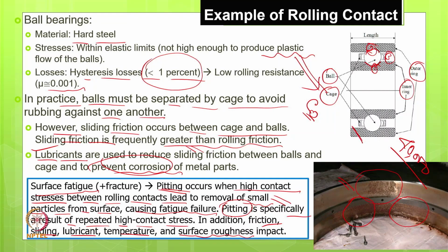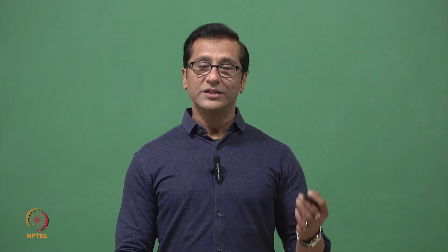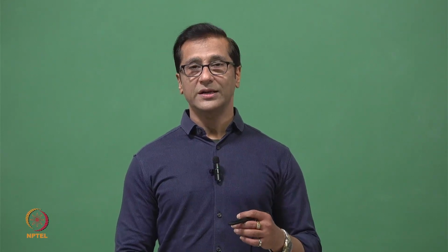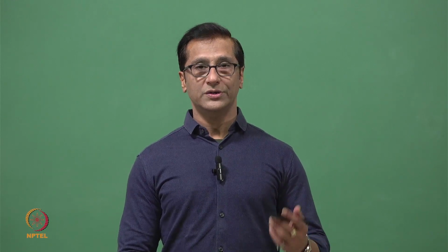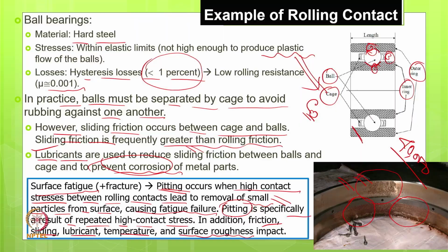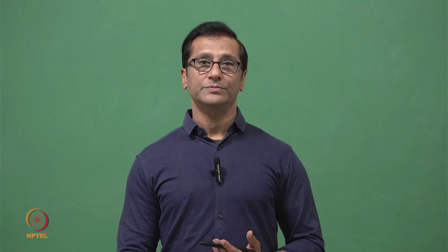In an emergency case, we also rotate this outer ring by 90 degrees or 180 degrees, so that it can sustain more cycles. So there is a possibility, but maintenance is important, and you have to think carefully about what angle to rotate, and that will give a good result. That's why it requires a little more domain knowledge. Pitting we are able to see, and it has sustained its life without any fracture. Many times people say it can be reconditioned, but reconditioning this big bearing is a bit difficult. However, with advanced technology, that can also be done.